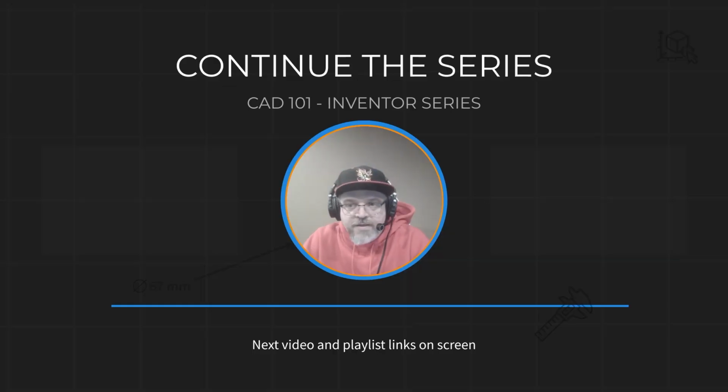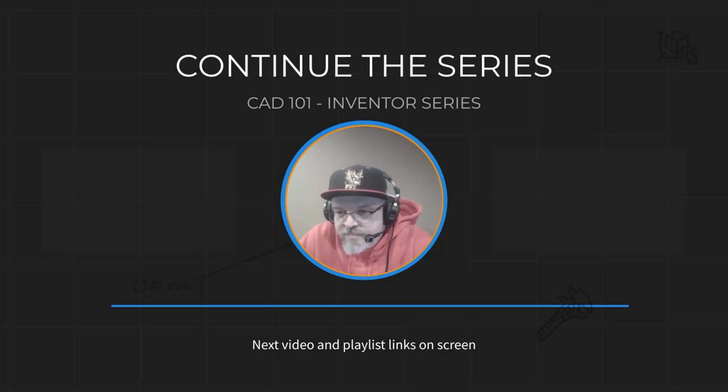All right, now you've got a sketch that actually works. We used lines, rectangles, and circles, locked everything in with constraints, and applied dimensions the right way, including a little bit of math. And this is the big takeaway. If your sketch isn't fully defined, your model is going to break later. So take the extra time here, because this is where good CAD actually starts. And remember, broken sketches don't get Drip King approved.